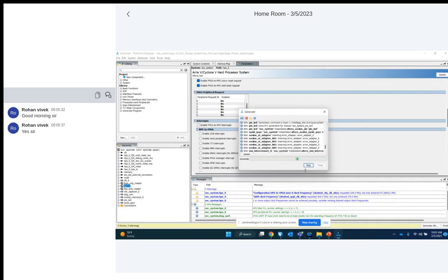So let it generate within a minute. Once we say that it is generated, we can go back to the Quartus. In the Quartus, we can do step by step. First, we can do analysis and elaboration. Then we can do synthesis, and then we can see how many reports, how many 7 input, 6 input, 5 input it takes, and then how many lookup tables, how many flip-flops, all that information. And then we can say how many memory blocks it takes on the processor side, I mean on the FPGA side. All those things, let us check.